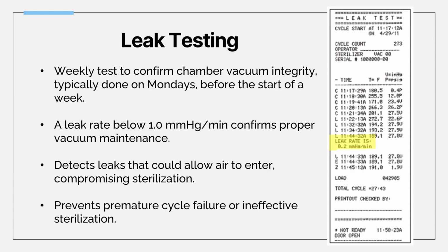Larger leaks must be fixed before the sterilizer can be used. So if there was a failure during the leak test, that means a technician must be called in again to ensure that all is working in the system. In comparison, Bowie-Dick checks air removal and steam penetration.